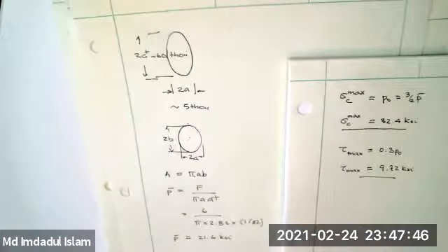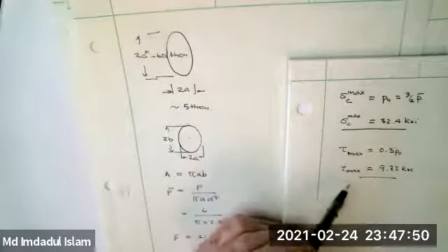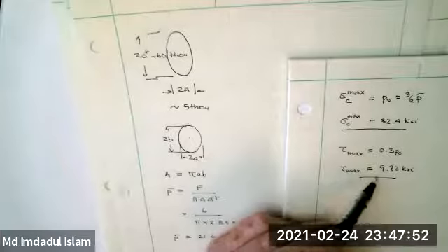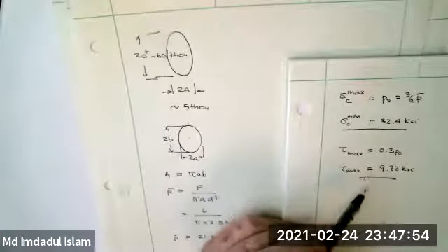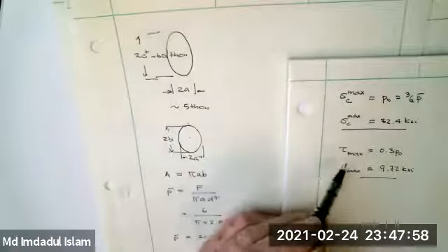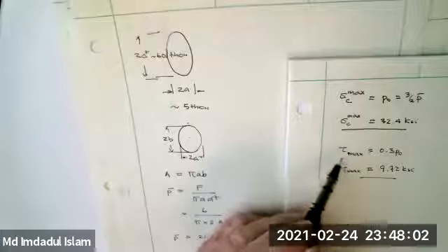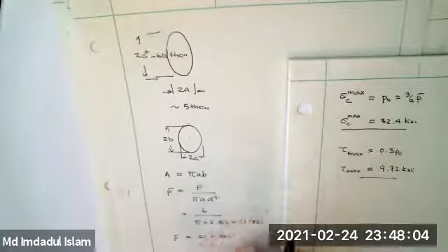Okay, and I'll get to your ellipse question. So this is 9.72. If it was A36 steel, it'd have to be 18, almost doubled. To get it to double, you'd have to increase that by a factor of 8 on your load, ballpark. Okay, so it's a long way from the load to yield for this bit.